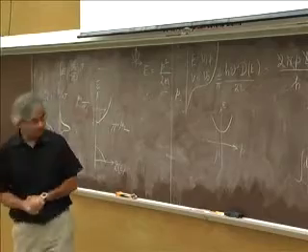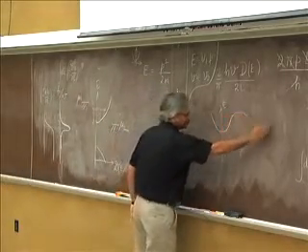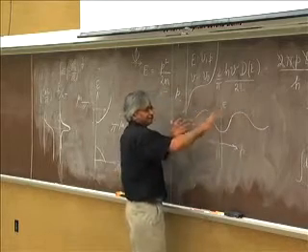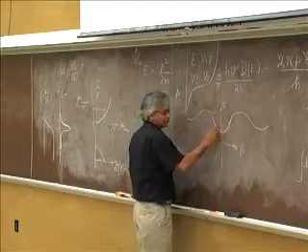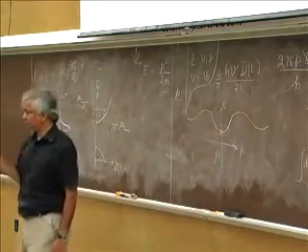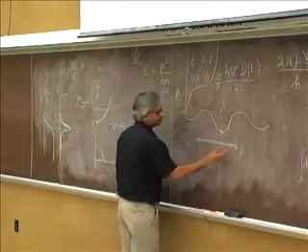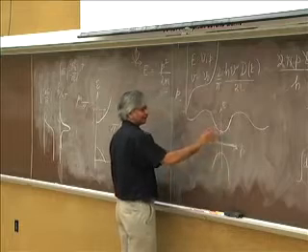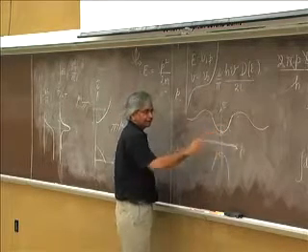What the E-p relation looks like there is really a fairly complicated function that goes on, and what you try to do is look at the minimum, because those are the ones that contribute to conduction usually. As I said, if your chemical potential is around here, there's usually a valence band and a conduction band, and you look at the minimum here and the maximum here.